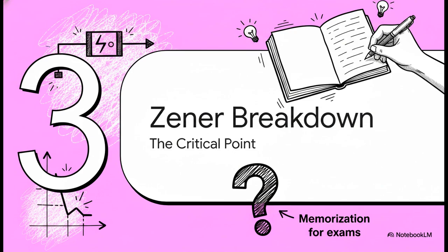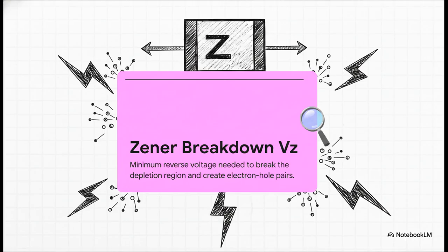Which brings us to Section 3, defining Zener breakdown voltage, or the critical point. This is the exact moment the physics completely shift, opening the door to its most incredible capabilities. Okay, so Zener breakdown voltage, or VZ for short, is the specific minimum reverse voltage required to break that thin depletion region and spawn free electron-hole pairs. Even though the barrier is super thin, you still need a minimum threshold of energy to get things going. The literal second you hit VZ, the electrons and holes in the depletion region absorb that energy, they break free, and suddenly, bam, you have a massive rush of free electron-hole pairs immediately ready to conduct electricity.